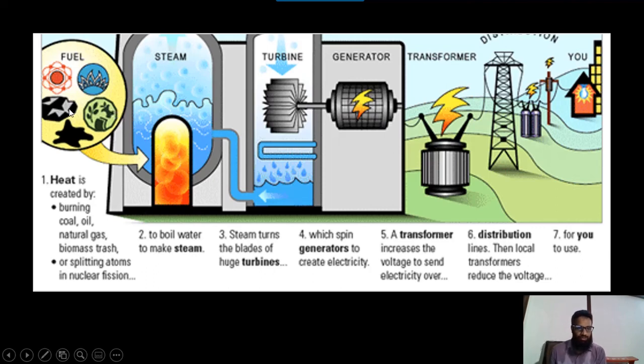We have solid waste. We put this solid waste in a reactor. It will burn the solid waste to produce heat, and this heat will produce steam, and then this steam, at almost 500 degrees centigrade, will be converted into dry steam, and this dry steam is injected into a turbine, and due to the pressure of the steam, it will rotate and produce electricity.